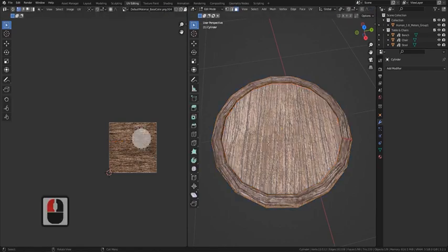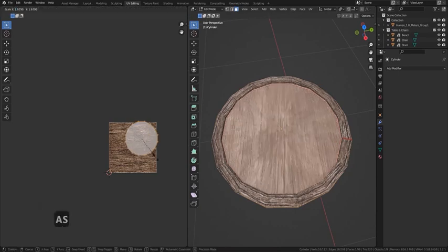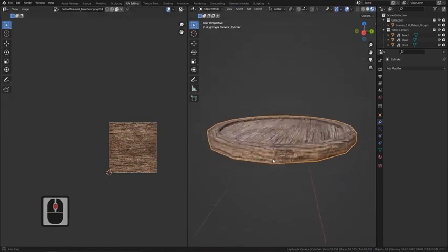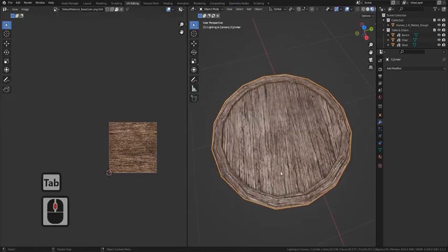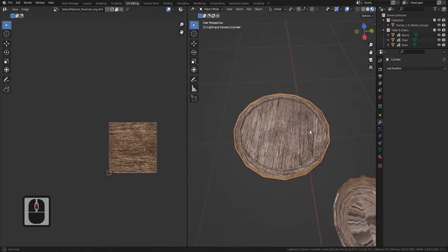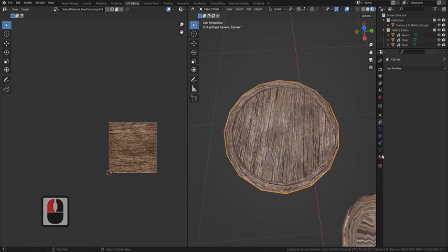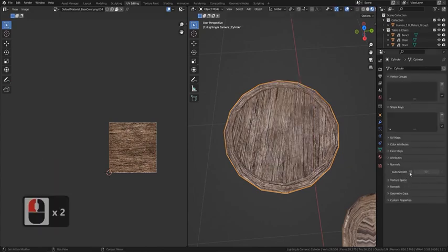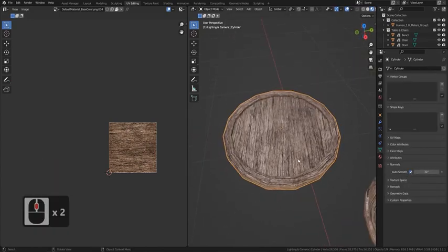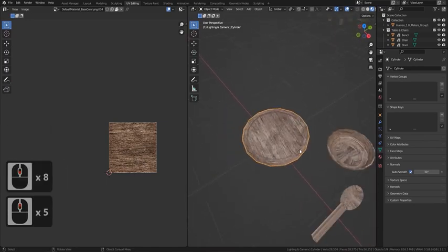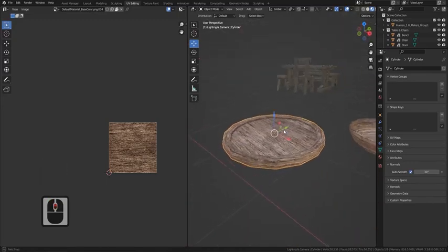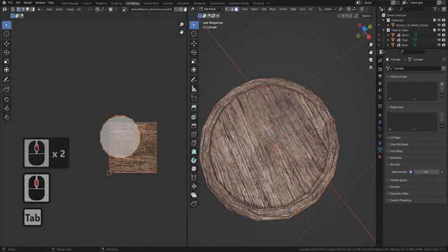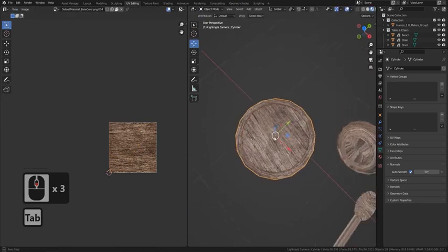So we'll grab it with face select. And I'm just looking, if I bring this out a little bit, yeah, that's going to look a ton better, as you can see. Let's grab the bottom of it, A, S, bring it out. And there we go. That's looking really nice. All right, let's shade it smooth. Bring in our auto smooth. And there we go. And then finally, I've not got any move tool in here either. So I'm just going to press your space bar, bring in my move tool, just so I've got that. And I'm thinking that I'm pretty much done with that, actually.